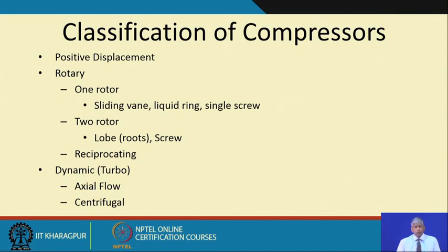So, you will see in industry many of these compressors you will come across. So, somebody asks you to find out the fault in a particular compressor. How do you do it? Well, thumb rule is measure the vibrations as close to the dynamics of the system, and that could be very close to a bearing, and again find out these vane pass frequencies, see if sidebands are there.